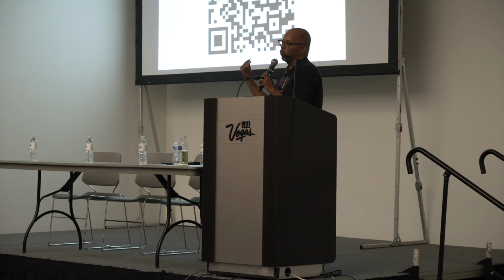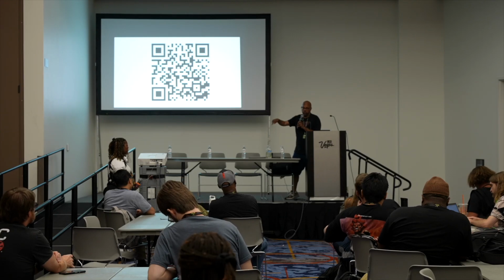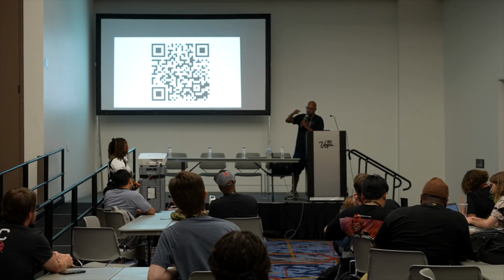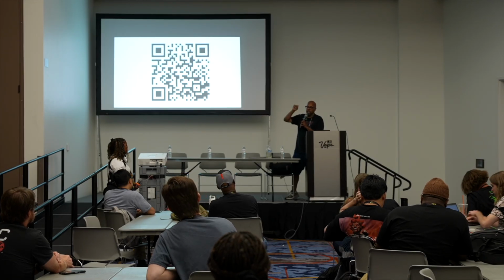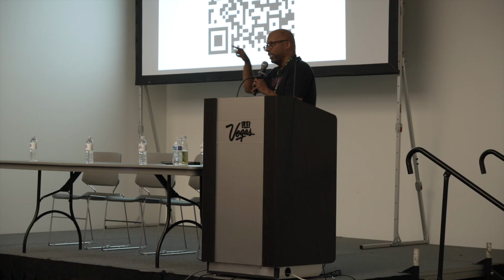You can get runtime information, like we use the Embedded Trace Macrocell, where you can follow all the branches. I have a paper where we follow the branches to see if malware is running, because if malware is running, it'll branch to the wrong location. If somebody did a buffer overflow and changed a return address pointer, it'll jump somewhere weird. So with one of these debuggers in real time, you can have another processor reading the branch addresses through JTAG or SWD.